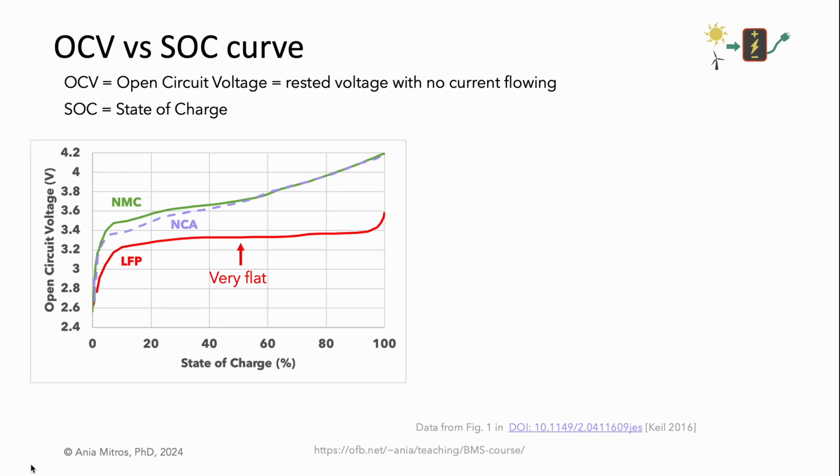Indeed, even with highly accurate voltage measurements, the cell voltage's time-dependent relaxation and temperature dependence can dwarf the voltage versus SOC relationship. We'll consider this more in the lectures on the value of accuracy and on balancing.